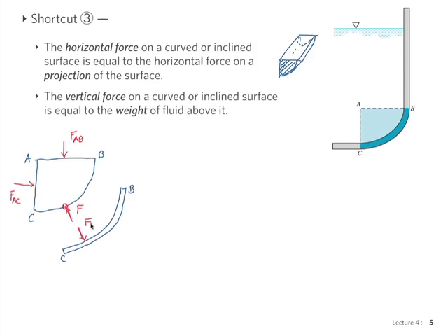So we're isolating the volume of fluid ABC times a unit depth. And you can see immediately from my picture that by isolating the volume of fluid, the horizontal force on this wall must equal the horizontal component of the resultant force, right? So in the horizontal direction, simply FAC is equal to the horizontal force.